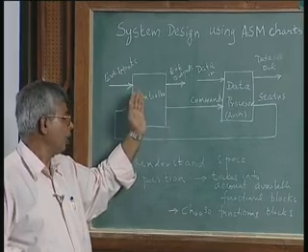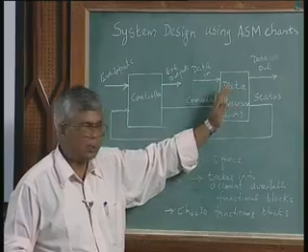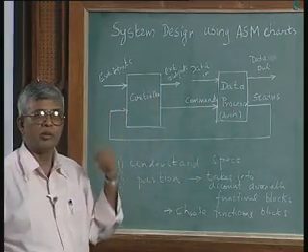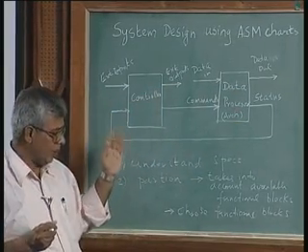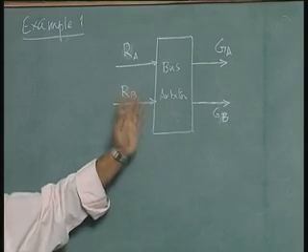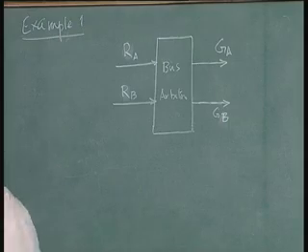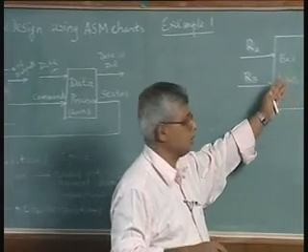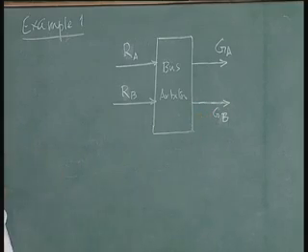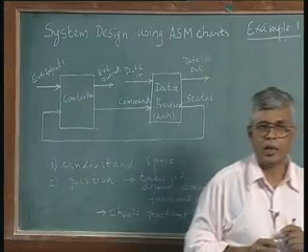I'm sort of putting some of the controller function into the data processor by putting an extra counter there. Otherwise, my ASM chart is going to be extremely big. So that is the approach taken. Here it is also very difficult to partition between bus controller and bus arbiter and anything else. Here it is only a simple circuit. So I am not going to try to partition this circuit into hardware architecture, functional unit and controller, because the first example I want to give is a simple example. I will straight away draw the ASM chart.